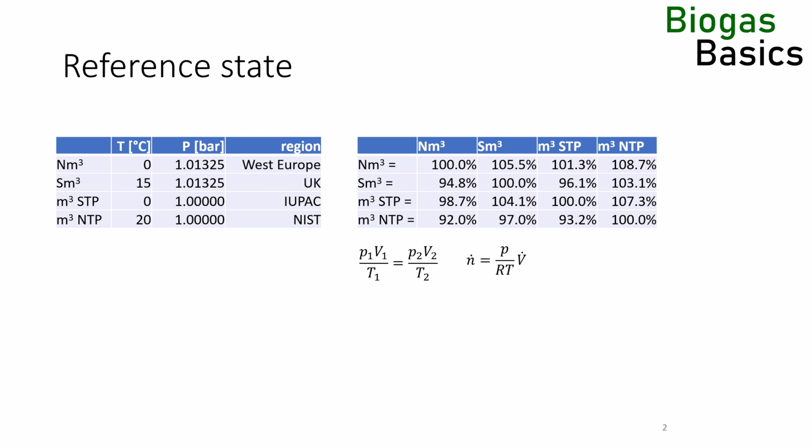The calorific value is given as upper or lower calorific value, also called gross and net, or superior and inferior calorific value. For the lower calorific value, all reaction products are in the vapor form. The upper calorific value includes the heat of condensation of water, so water leaves the combustion as a liquid. Efficiencies of CHPs or internal combustion engines are typically stated related to the lower calorific value. In the biomethane or renewable natural gas market, the upper calorific value is typically used.